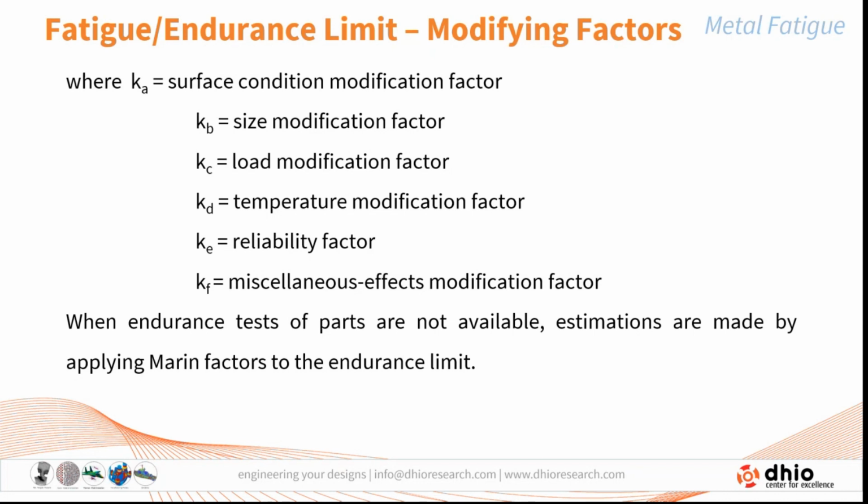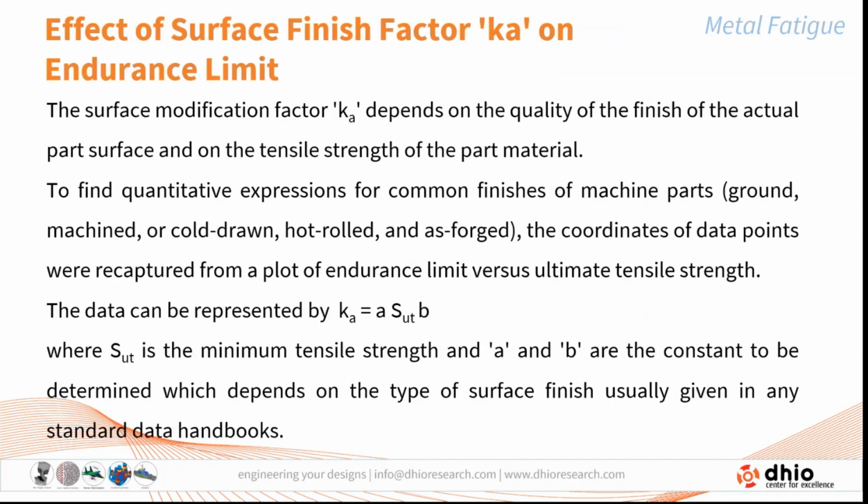Now, when endurance tests of the parts are not available, the estimation of the life of the component can be made by using the Marin factors to predict the endurance limit of the component. Now, let us take one by one, starting with the effect of the surface finish factor Ka. The surface modification factor Ka depends on the quality of the finish of the actual part and on the tensile strength of the part material.